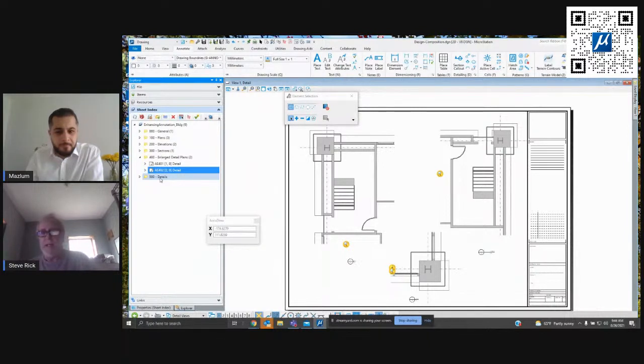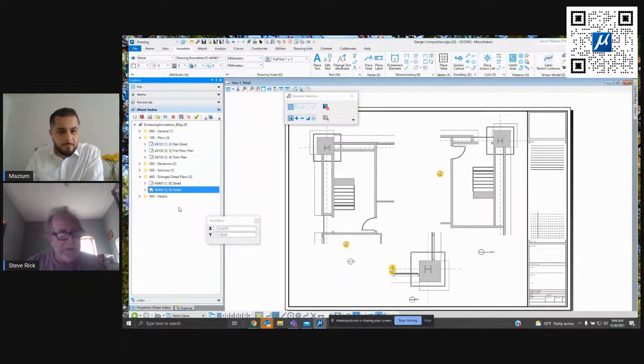Or let's say I have to create 5 more floor plans, so I'm going to put 5 more sheets in here. Well, I've already got my details and my sections way out here, numbered according to these sheets up here. If I drop any sheets in before that, it renumbers the whole list of sheets, and I don't have to do that, especially if I'm doing sheet 1 of 200 and 2 of 200. I'm sure everybody has felt that pain, right?